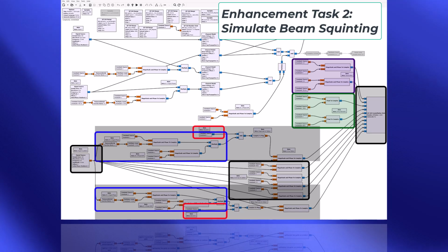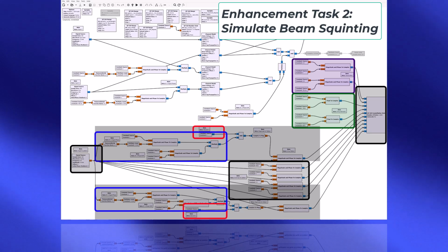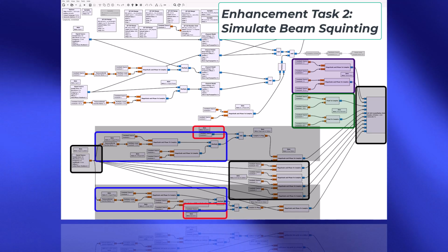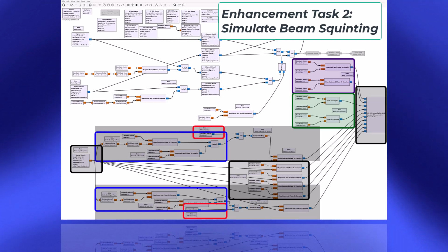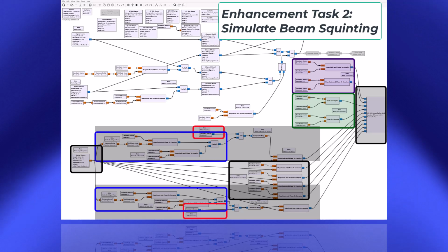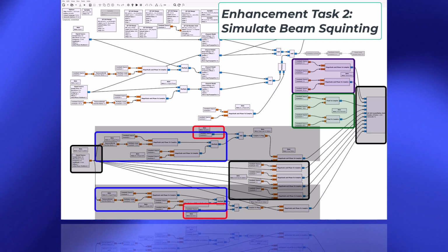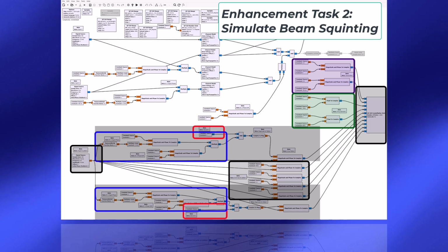And the basic way to implement that is to assume, as is done in the original simulation, that the element pattern that you see is generated based on the assumption that the element spacing in wavelengths is as you've selected using the slider for some nominal or reference frequency. That frequency is implicit right now, so we'll just consider that as a factor of 1 and consider any other frequency where those transmitted signals might actually be as a proportion of the reference frequency.